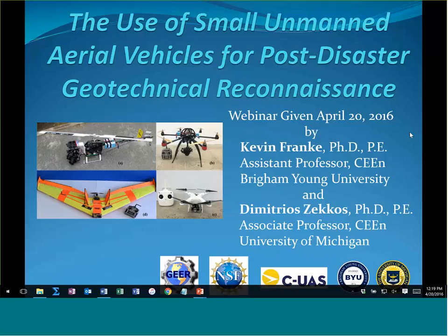Some of these quadrotors have 20-minute or so flight time, and so you may have to land and come back to do this. This is also the difference between the fixed wing and the quadrotors, that the quadrotors can actually stay in one place and zoom in more and go up and down, while this is much more difficult, possible actually, for fixed wing. And so again, that's where we're talking about the type of drone that you have also will affect the type of data you can collect.